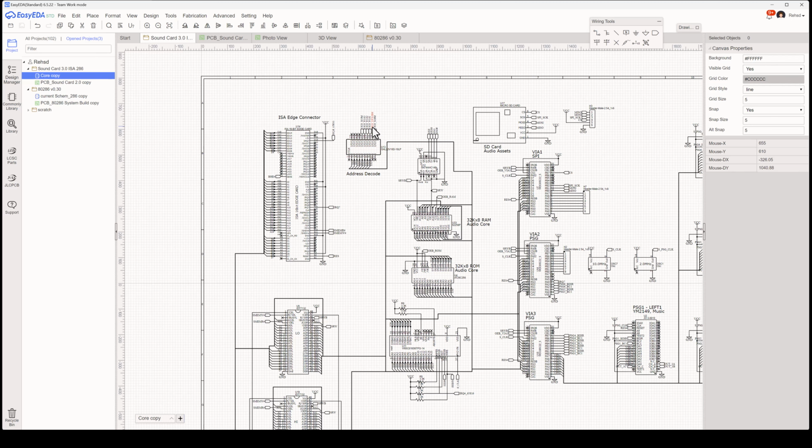This OEB, this output enable bar for DP RAM, I do use that down here in my logic. So if I want to, on the internal side of these dual ports, enable it for the 65816 to read, write, etc., I leverage that signal coming out of the PLD along with the A0 for the sound card. If it's low, then that enables one chip, and if it's high, it enables the other chip. So the 65816 doesn't know or care that there's two separate chips here. It's just whether it's an even or an odd address, it'll automatically bounce to one dual port static RAM or the other.